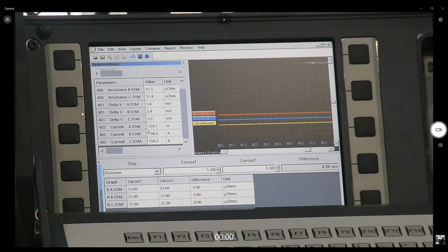If I had a generator circuit breaker, which has very low ohm resistance, I might have gotten up to 250 ampere for the measurement. So this is basically SRM. I did the test on that breaker while it was closed, and this is the measurement that I got.